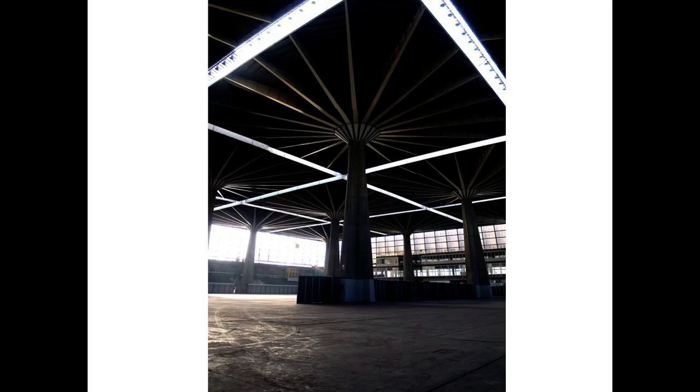Absolutely beautiful building. All it's doing is containing whatever it has to contain. It's an industrial building, isn't it? But it's a series of umbrellas in a way that's keeping the rain off and the wind off. And the umbrellas are concrete columns with steel girders coming out from that central point there. You might notice also that the columns are tapering, as I said before, because the mass is growing, isn't it? It's getting heavier and heavier as it comes down.